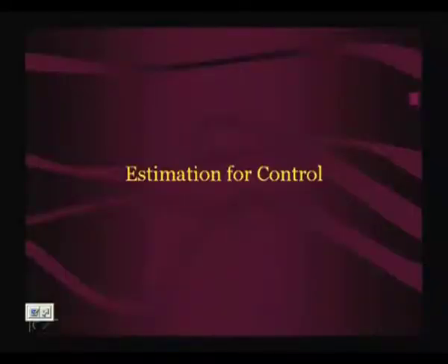But we took some relatively simple measurements from some sensors, set up a model, and built an estimator which gave a fairly correct value of the tool wear online while the machine is cutting. It can predict what the present value of tool wear is. So that is what estimation can do for the field of measurement.